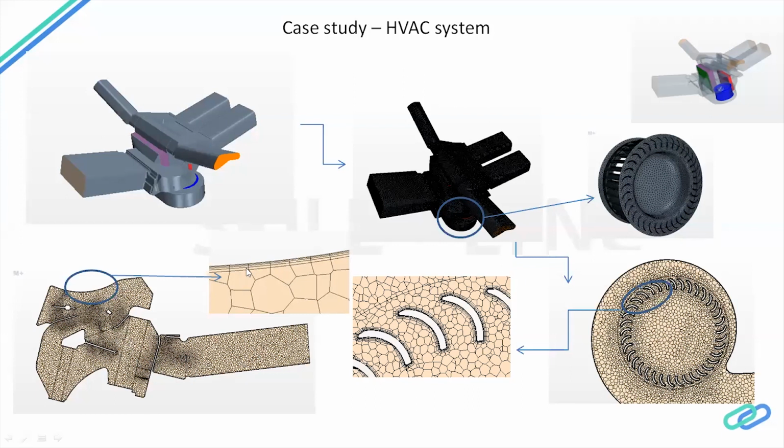So in engineering we can study the boundary layers. The purpose of the boundary layers is to capture the fluid behavior with respect to the walls. Whenever the fluid is passing over a stationary object, we have a no slip boundary condition. Because of the no slip boundary condition, we have a boundary layer.